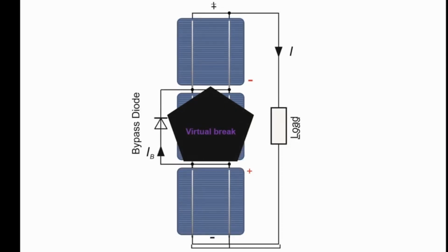How can we overcome this? This is via a bypass diode. This is a diode that is without function under normal conditions. So if this cell is fully illuminated, there's plus minus. So plus minus at this bypass diode means it's in blocking condition. It has no effect at all. And now if we have this reverse voltage, minus plus, it's in conducting condition and the current is deviated around the shaded cell, and we still have a considerable current going through the whole system here.